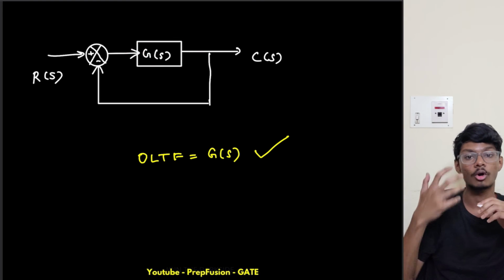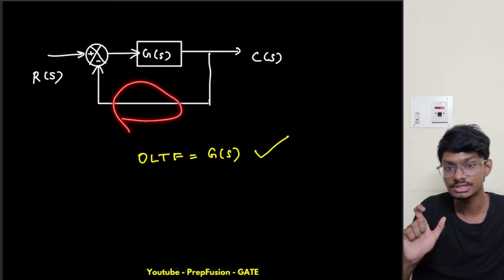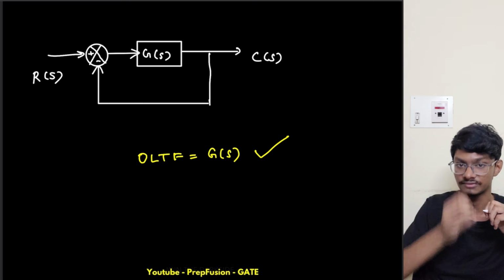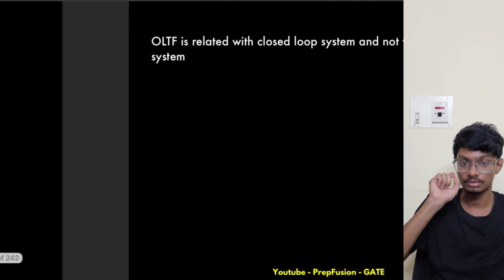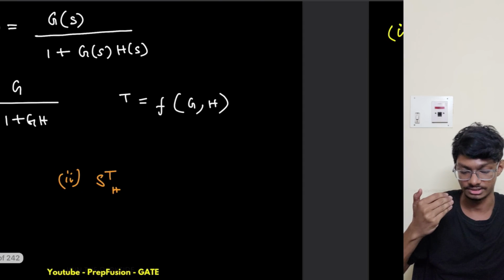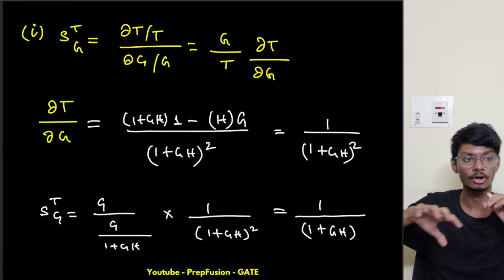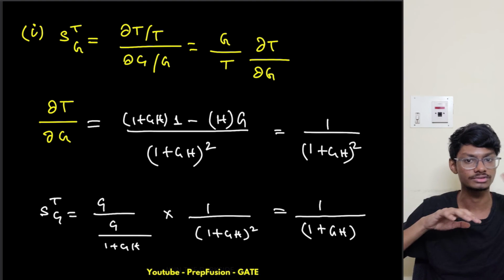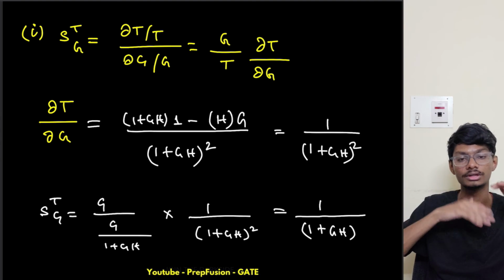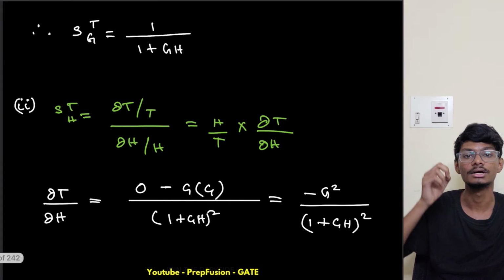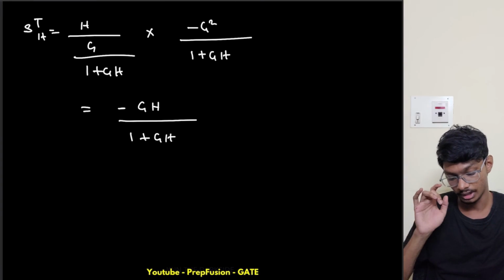to make it less sensitive to changes in the system. But the drawback is, if there is some change or disturbance in the feedback, then the system will be more sensitive to that change. By sensitive I mean, if there is a change in the feedback, the output will also change much more, but we don't want it to change. We want it to remain stable in the desired output range. So that is a drawback.